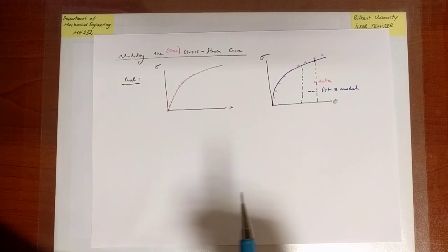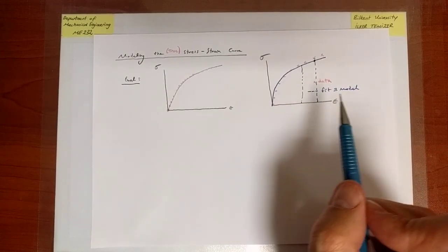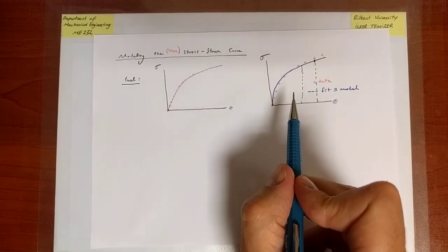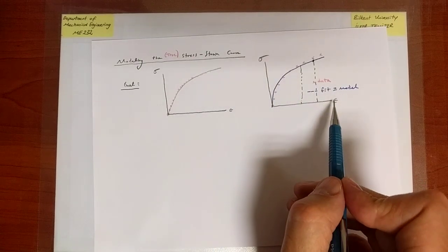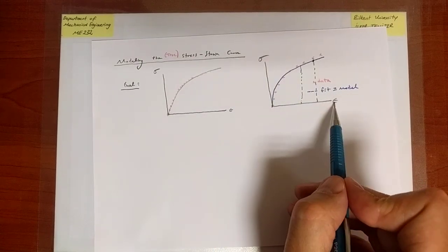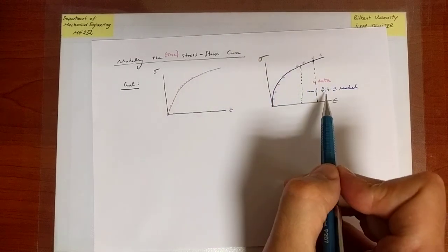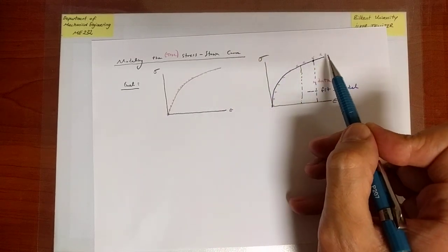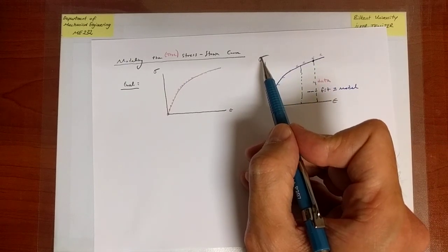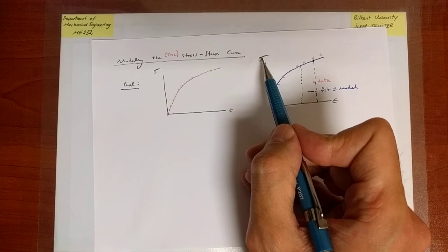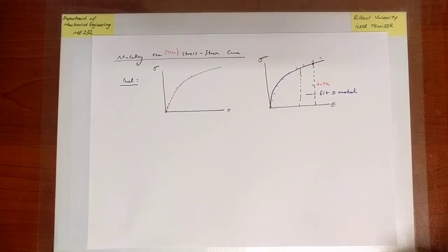All right, so why do I need a model? Well, because the stress-strain curve gives me information about the engineering stress at a given engineering strain. Engineering strain is deformation, engineering stress is load. So this curve, in other words, this nice mathematical function between deformation and load is going to help me design procedures that are typically, for instance, used in manufacturing operations.